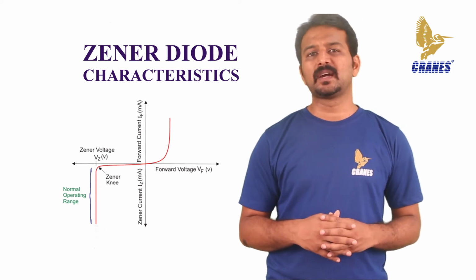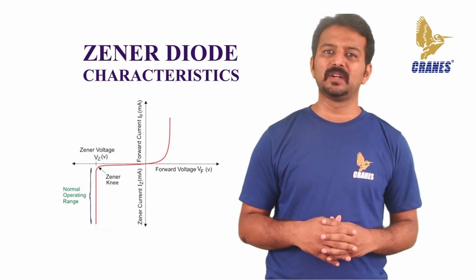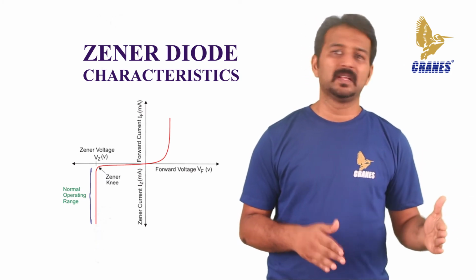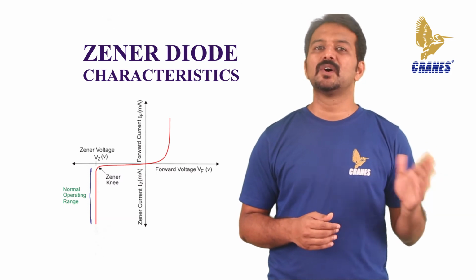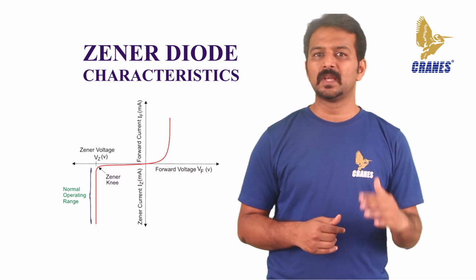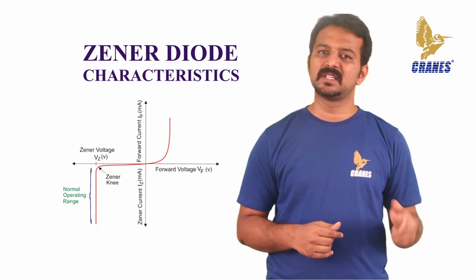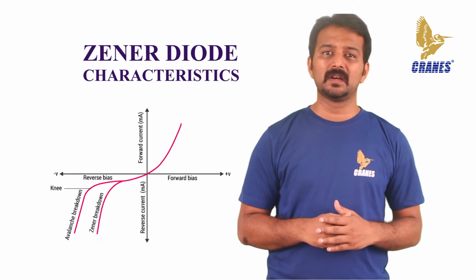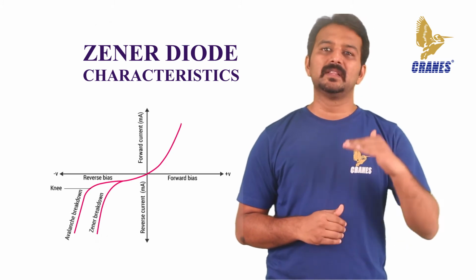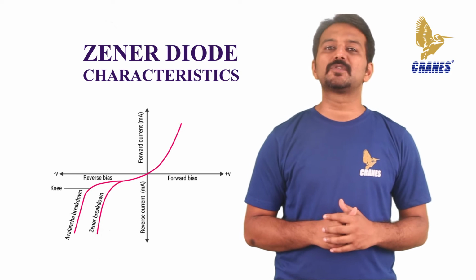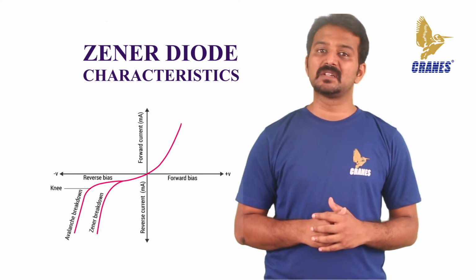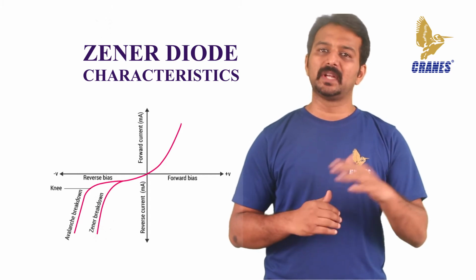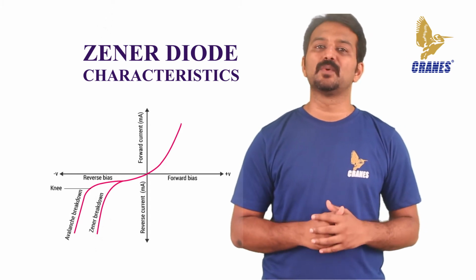However, unlike a conventional diode that blocks any flow of current through itself when it is reverse biased, that is, the cathode becomes more positive than the anode, as soon as the reverse voltage reaches a predetermined value, the Zener diode begins to conduct in the reverse direction. This is because when the reverse voltage applied across the Zener diode exceeds the rated voltage of the device, a process called avalanche breakdown occurs in the semiconductor depletion layer, and a current starts to flow through the diode to limit this increase in the voltage.